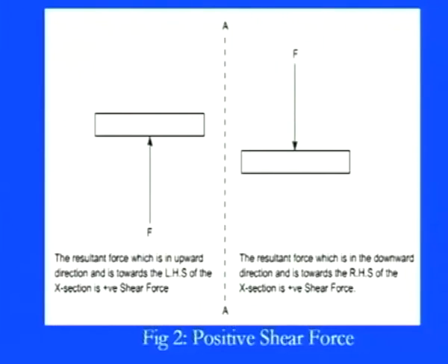Just keep this in your mind: whatever the point applications are, the reaction is going in the upward direction and the applied force is in the downward direction, then whatever shearing is coming in between this section is the positive shearing force.